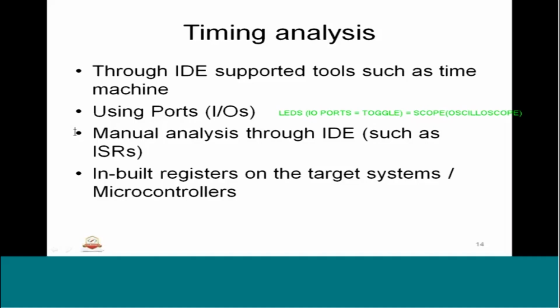With the help of that, the timing can be tested where the embedded software will be triggering upon certain events, and those events can be captured in the oscilloscope. And for ISRs, we can analyze through the IDE, where in the ISRs we can have a counter and see how much the counter is getting updated. The counter also can have registers. The timing registers can be used along with the counters to arrive at how much time it has taken. So manually this will be done to analyze the ISR timings, etc.